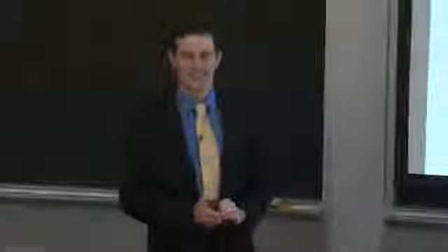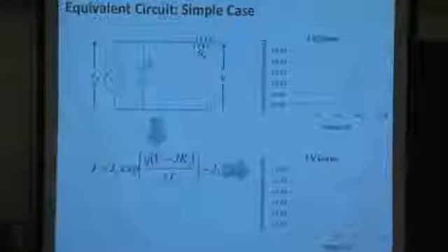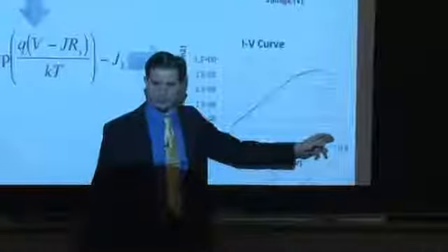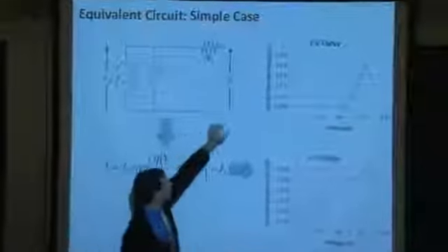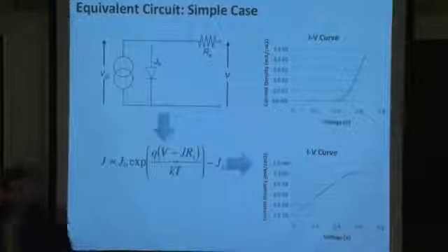That's the goal. And this is not voltage out, this is voltage applied to the battery. No, this is the voltage that is being measured across the solar cell. Mm-hmm. The output voltage, yeah. Mm-hmm. Or you can think of this as the biasing condition of your solar cell device. The two are almost equivalent. The only difference is you have that series resistance in series there, so you have to be careful whether you're talking about the voltage here at the solar cell itself across the junction, or the voltage coming out of your device that is affected by that series resistance as well.